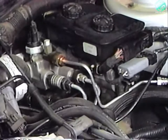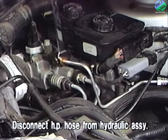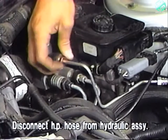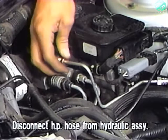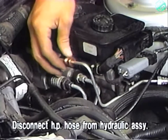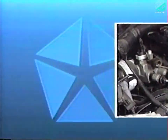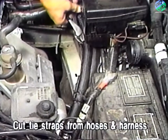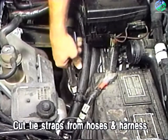To replace the high-pressure hose on the BB Body Eagle Premier and Dodge Monaco vehicles, also begin the procedure by disconnecting the hose from the hydraulic assembly. For visual clarity, the air cleaner assembly has also been removed. Next, cut all the tie straps attaching the high-pressure hose, low-pressure hose, and wiring harness together.